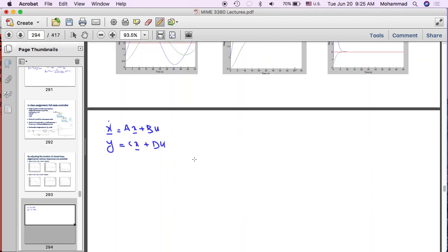So what did we say? We said in state feedback plus pre-filter, if that is the case, the input to the open loop is KR, the pre-filter, times R, the reference input, minus K times X, where both K and X are vectors.